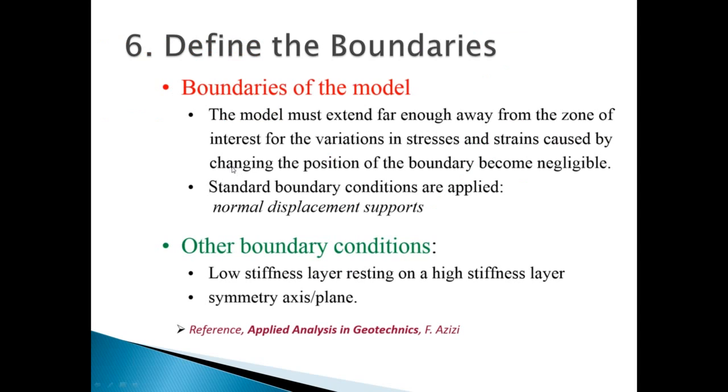And then defining the boundaries. Okay, so something that's really important to keep in mind is that when you create your boundary conditions, you want to make sure to include enough area to include anything that would be of interest, but you don't want to make it so big that the analysis would become longer. So this is just another way to make sure that your analysis doesn't take too long: create your boundaries according to the rules of the slides, which I'll show you.